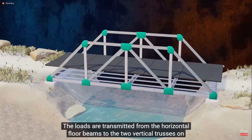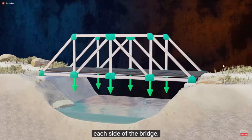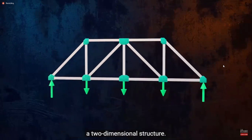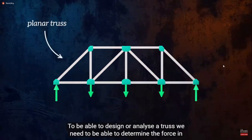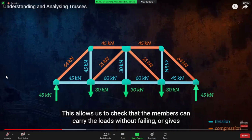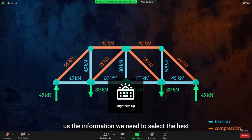The loads are transmitted from the horizontal floor beams to the 2 vertical trusses on each side of the bridge. Each of these trusses only carries loads acting in its plane, and so we can analyze it as a 2-dimensional structure. To be able to design or analyze a truss, we need to be able to determine the force in each of its members. This allows us to check that the member can carry the loads without failing, or gives us the information we need to select the best cross-section for each of the members.